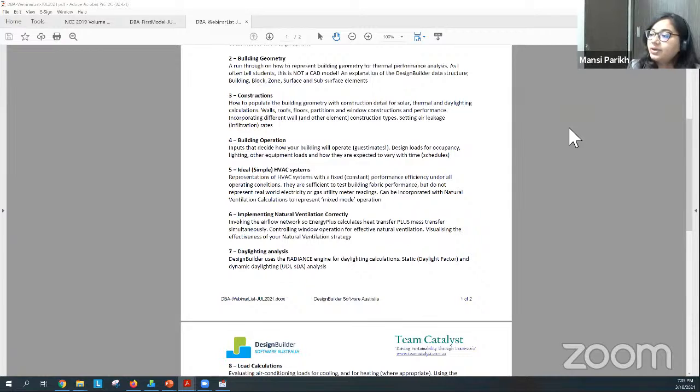Again, when we went from 1.4 to 0.8, there was a 13% reduction. When we went from 0.8 to 0.4, that reduction was 13.4%, and from 0.4 to 0.2, the reduction in annual cooling load was only almost 2%. So there was not a significant reduction in annual cooling load. However, the cost of insulation would triple.